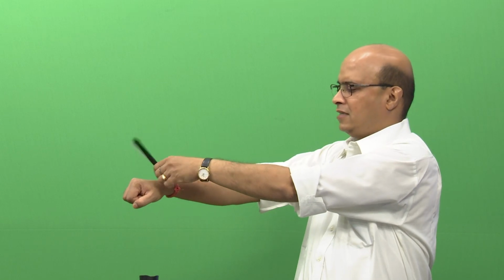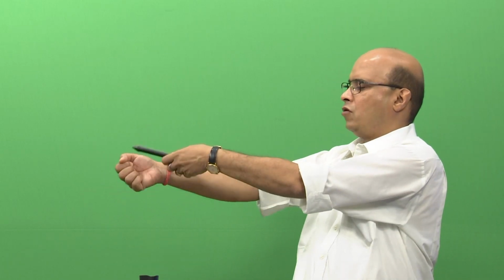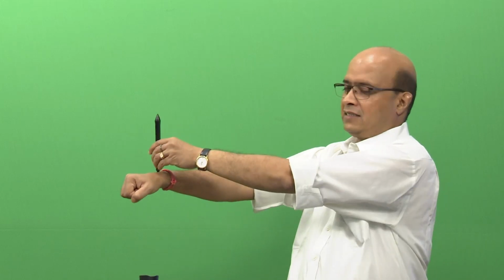Now, in the human hand, the roll axis is from here. So we have a combined elbow joint. In the human case, the roll axis comes here. So in the human, we have a different wrist, where the last 3 axes are not intersecting. Please note that in the case of the robot, the last 3 axes are intersecting at the wrist, which is my roll, pitch, and yaw. They are all intersecting here. Whereas in the case of the human hand, they are not intersecting, because we have the roll which takes place from here.